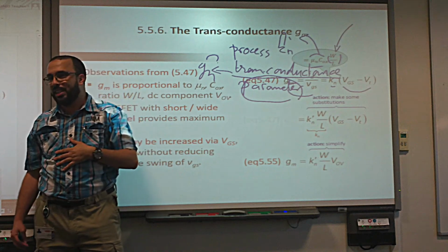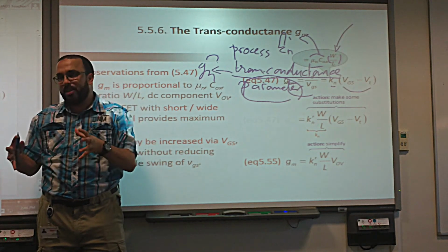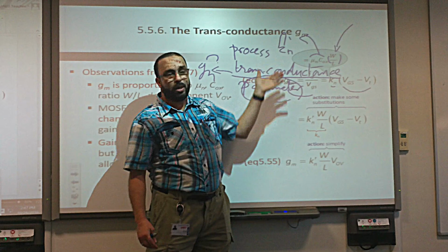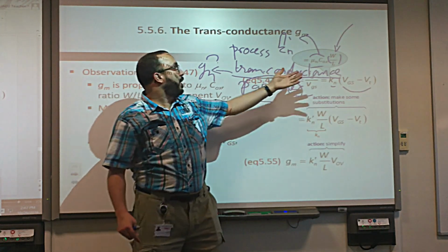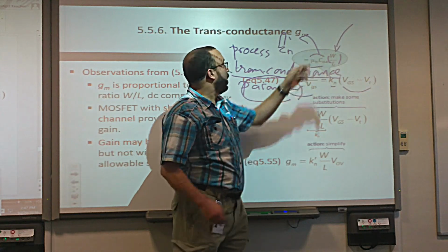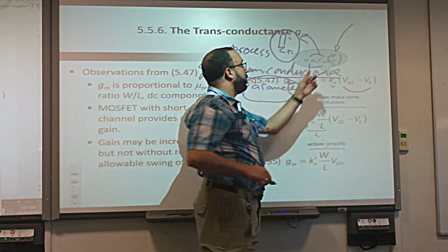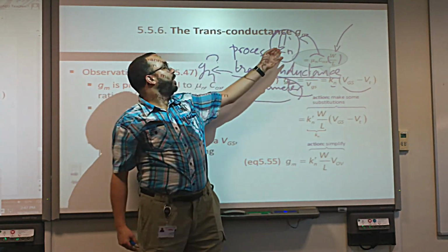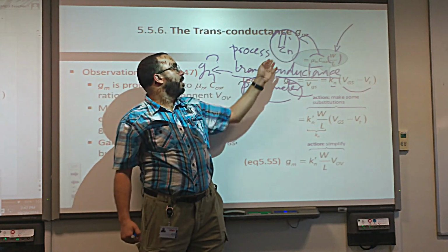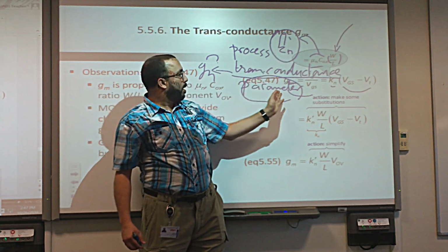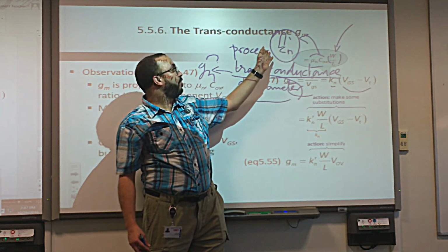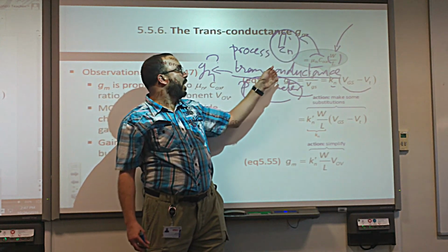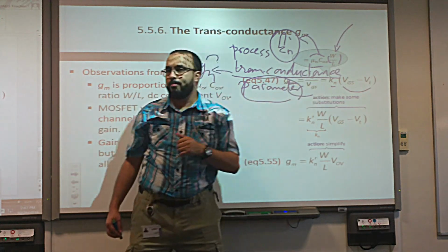Do you understand? So it's a parameter inside the transconductance that is related to the process. And because the English language likes to make things squeezed, they call it process transconductance parameter. We are talking about Kn prime, which is mu n Cox. The name is like this, but the definition is that it is a parameter related to the process, fabrication, that is inside the transconductance.